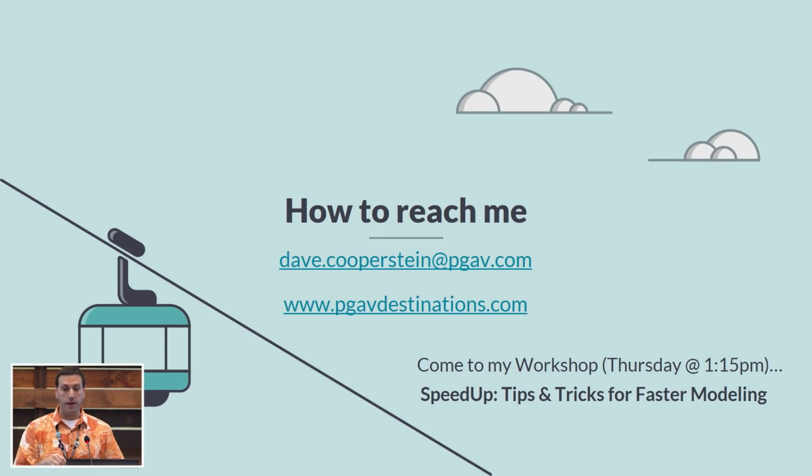I went into the model, and every button and control panel and the seat belts were still in there, but they had shrunk it down to a tabletop size because it was for an exhibit. It was basically the entire space shuttle sitting on a table, and I didn't need it. So I deleted everything on the inside, and it shrunk the model by hundreds of megabytes. So just go in and look at it, see what you don't need, delete it.